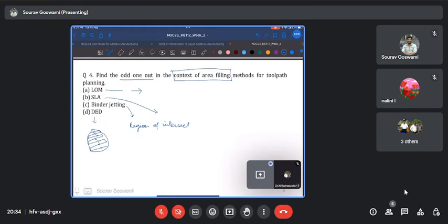And in each layer, I'm focusing only on the region which is actually my part. I am less bothered about this surrounding region of the build plate. And so I concentrate my toolpath planning efforts on filling this contour only. How my toolpath will travel within this contour, or how it will deposit the perimeters and such other steps.